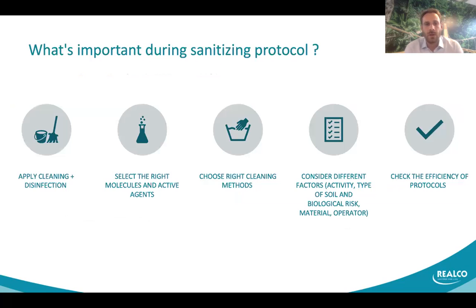So this slide is just showing you what you have to design. Basically, the first thing is to choose the molecules you are going to use for the cleaning and for the disinfection. And when you have decided the molecule you are going to use, depending, of course, on your process and the area where you are going to apply the product, you have to follow the operators. So you have to design the protocol, step by step.